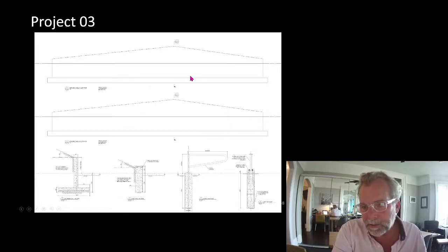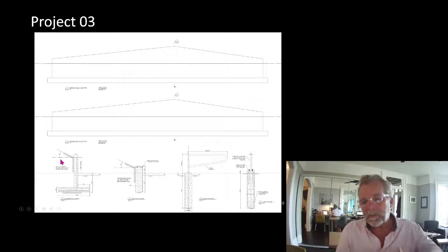Here we've got a big retaining wall. So this is an elevation of the retaining wall. Here's a section through our retaining wall. A number of things to note. One is you can see that this is a fill situation. So we put most of the footing on the high side. You can see that there's a slope here. That slope is actually meaningful.